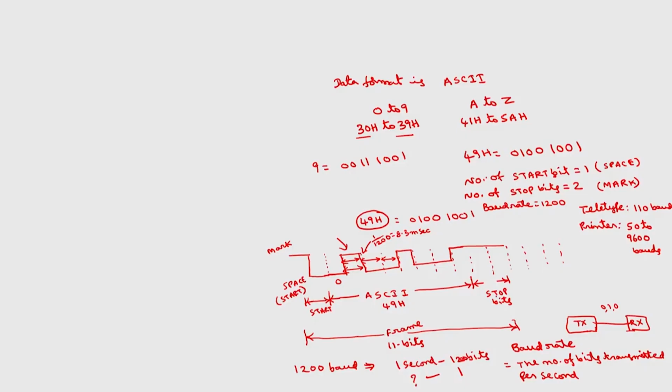So, see how we can transmit the data in the asynchronous mode of serial communication. We require start and stop bits. Normally, because of these start and stop bits, the rate of data transmission is lower. So, we have to use this type of data transfer for data rates less than 20 kilobits per second. This is one difference between synchronous and asynchronous data transfer.